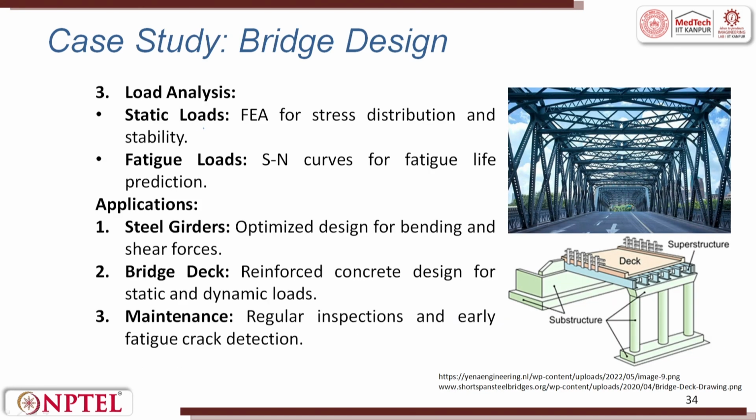The load analysis: for a static load, FEA for stress distribution and stability is done. For fatigue load, the SN curve for fatigue life is predicted. These are the considerations for a bridge, and whatever we have considered can be used in making steel girders. Here the optimized design for bending and shear force is taken. For the bridge deck, reinforced concrete design for static and dynamic load is done. Maintenance, regular inspection and early fatigue crack detection are also considered in the bridge design.